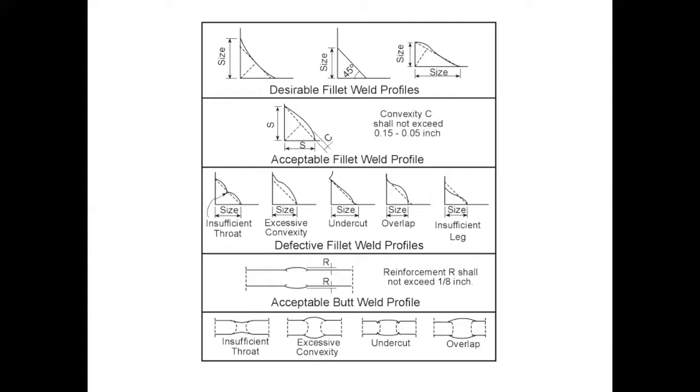And then also what happens is as water flows, if you guys have ever looked at a river, you see water will be nice and flat, and then it'll hit a big rock in the middle, and you'll see those swirls on either side of it. That's a vortex or vortices. And what happens is those vortices, as the material flows over it, it gets turning, it gets spinning, and then that material spins and wears against the inside of the pipe.